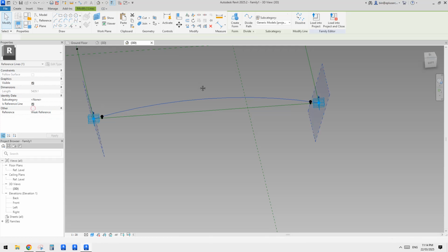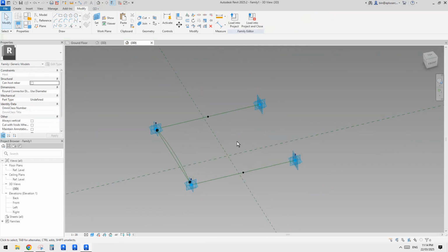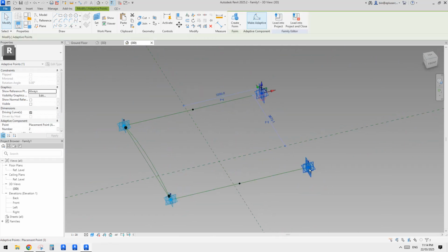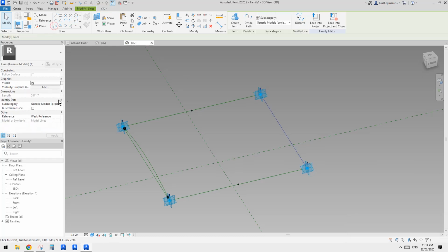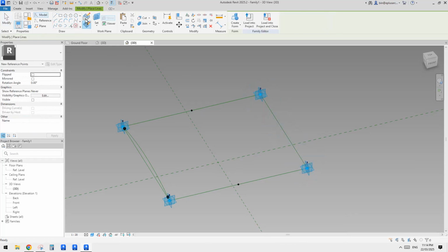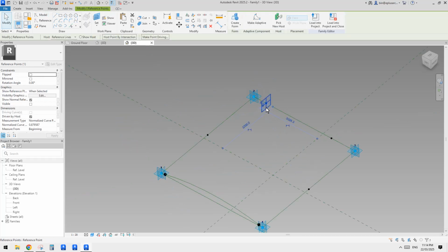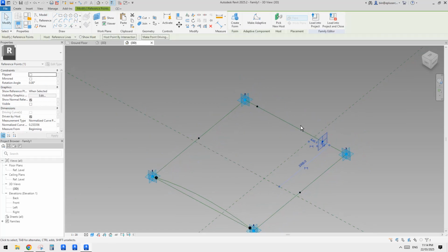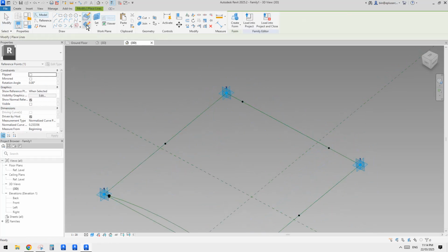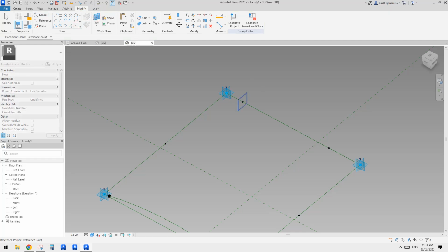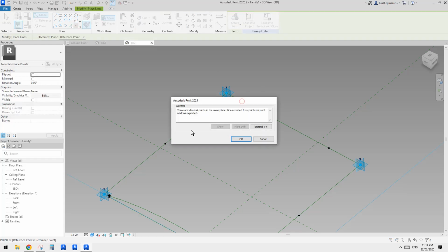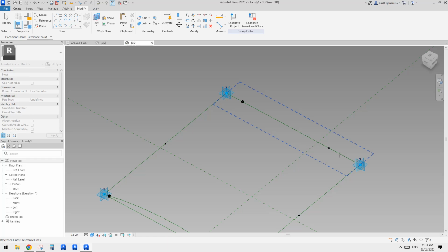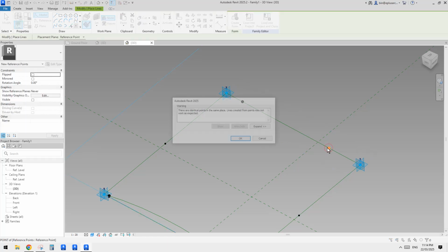So we have this, right? And for the next one, I'll just quickly do it. Spline through points, draw on world plane, so 1 and 2, measure from this side, and place a point, draw on world plane, set world plane, tab, place, okay, set world plane, tab, place, okay.